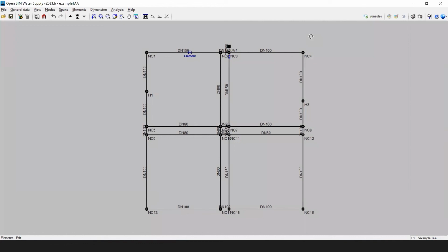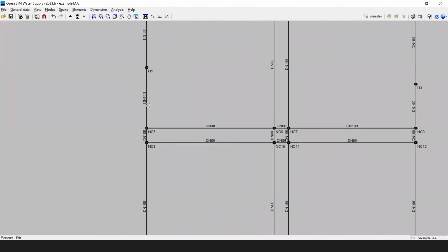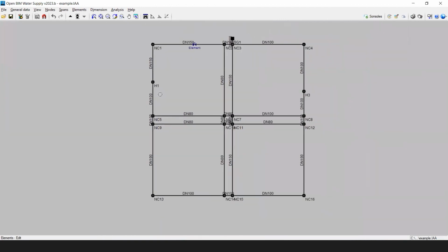water supply system. So one other difference, and it is not in the use of the software, but just for everyone to know, in the other one, like sewage systems, they can only be branched. Okay, can only be branched systems. In this one you see that the water to this node can either come from this or this span. That's called a gridded system. So only for water supply, we can generate actually either branched, gridded, or mixed systems, both of them.